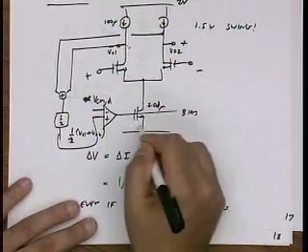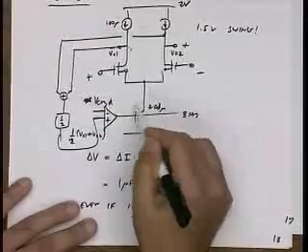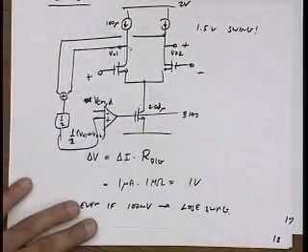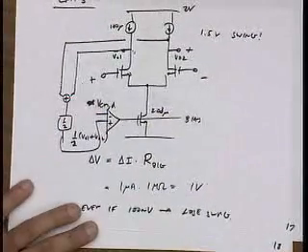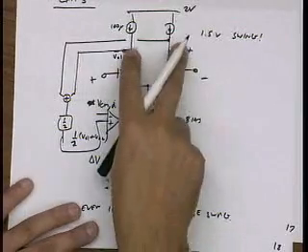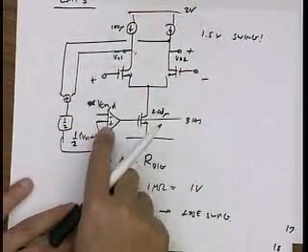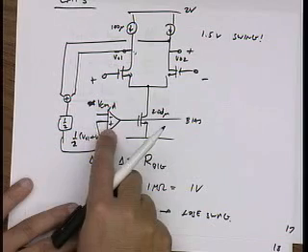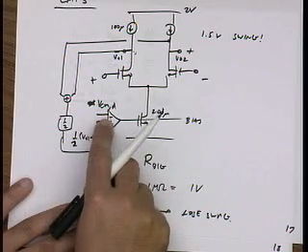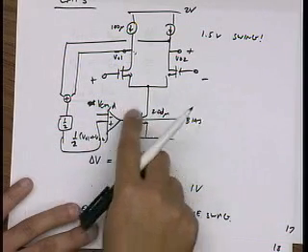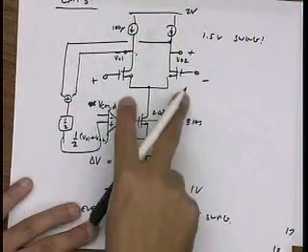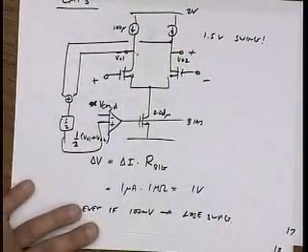Since this is an inverting stage, this is a feedback loop, I hook up my differential amplifier here, and I'm set. If the common mode is too high, this voltage is bigger than this voltage, so I apply big voltage, that increases the current, which pulls this down low, and vice versa.